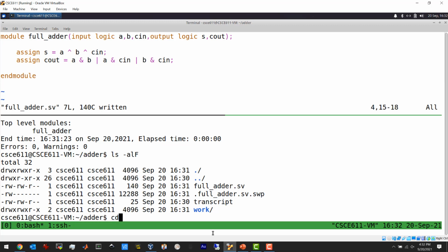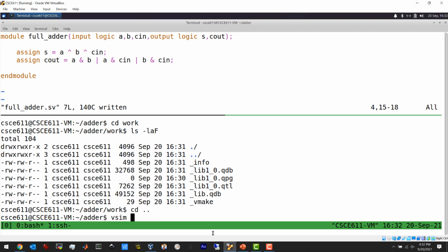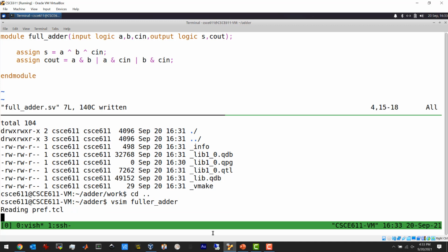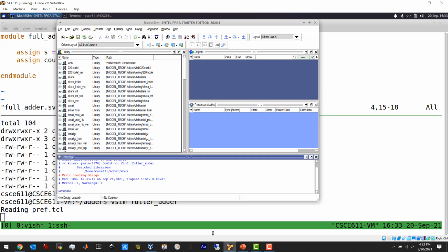Okay, and if I go inside work, by the way, I don't know what all this is about, but there are just some nondescript files in there that are the output of the compiler. Okay, then I use vsim. Sorry about that. So vsim, what did I call it, full_adder. Okay, so there's vlog and vsim, and you'll probably at some point get them confused like I did. But vlog is compile, vsim is start the simulator. And I screwed that up too.